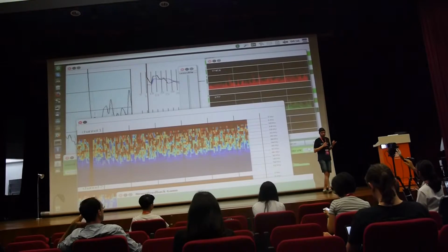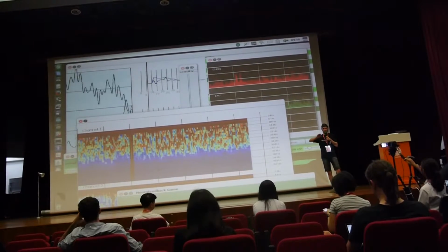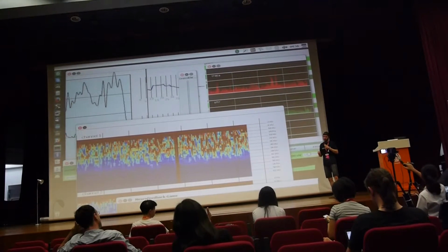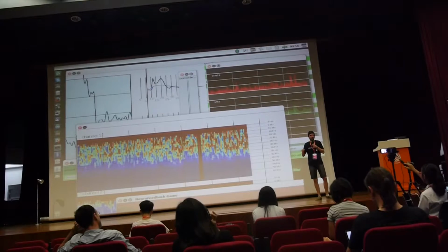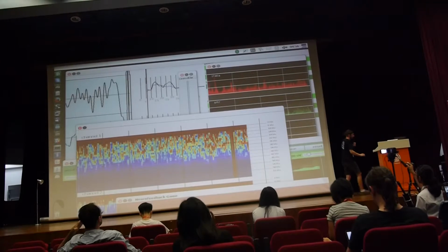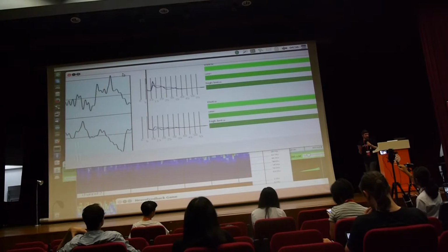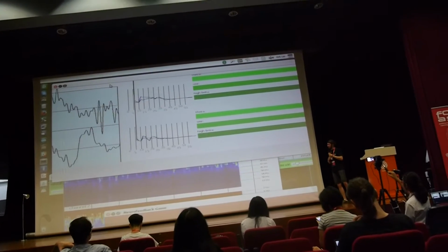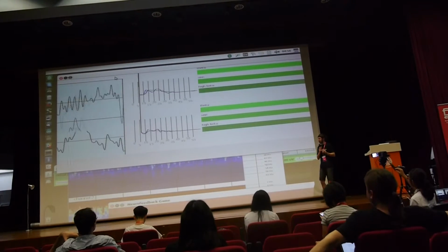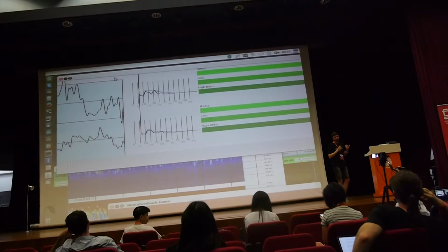Yeah. Basically, because you have effects like the DC drift, because of how the reading works, what you want to do is called a DC drift correction or a baseline correction. As you can see in the raw data plot here, it's kind of moving up and down, so what we first have to do is remove an average signal value. This is baseline correction, and then you also do filtering, something like a bandpass filter.